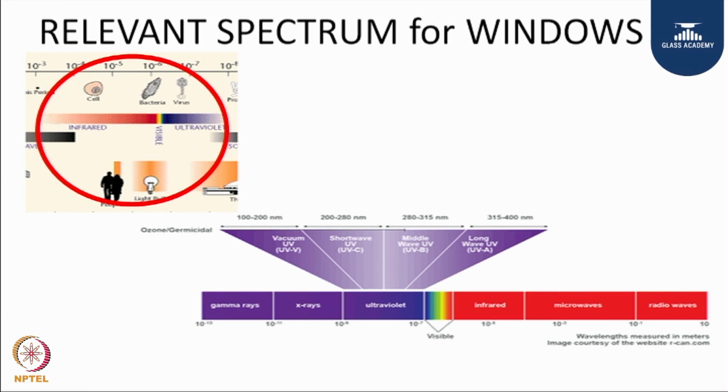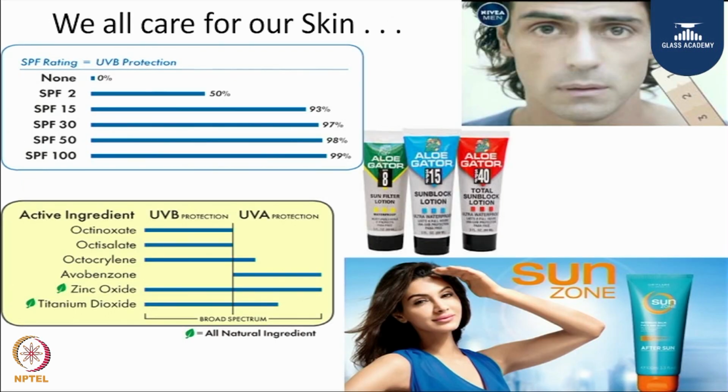As we discuss ultraviolet, let me give you certain examples of how it works for us. Ultraviolet light is detrimental not only for PVC but for any plastics, because the wavelength is such that it interferes with the polymer chain and eventually disintegrates or degrades the plastic. However, the slide on the screen is more relevant to give you a correlation with the creams we use in India or in a tropical climate or anywhere for sun protection.